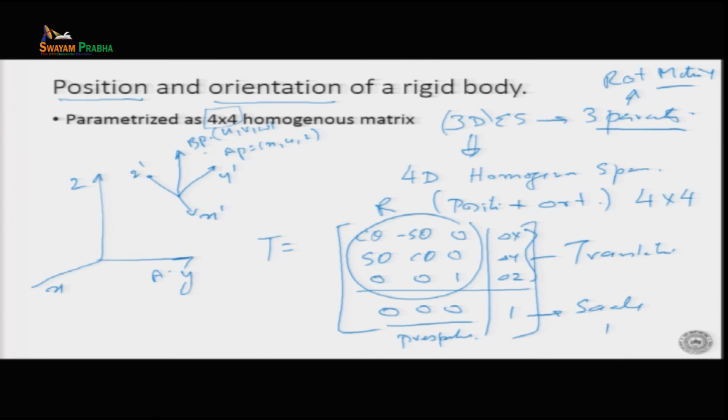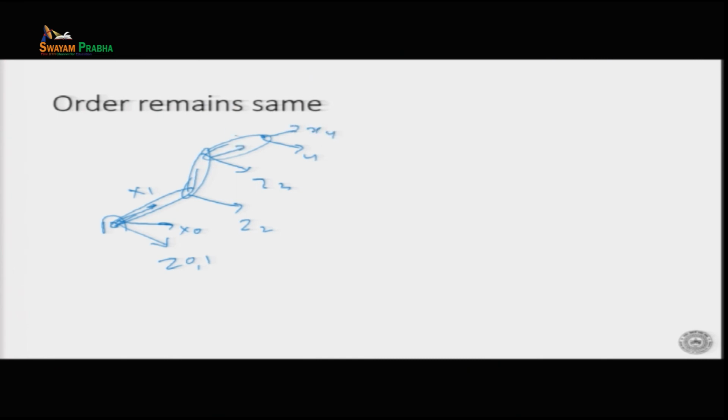Now, something to note about this is that when we are going from here to here, I have frames which are assigned Z0, Z1, Z3 and Z4. So, this is my x axis, these are the various x axes, this is x4, this is x3. Now, if I want to find the relation between that one and the 0 frame, then it is basically T0 to 4, and I find the matrices between each of the frames and multiply them out.